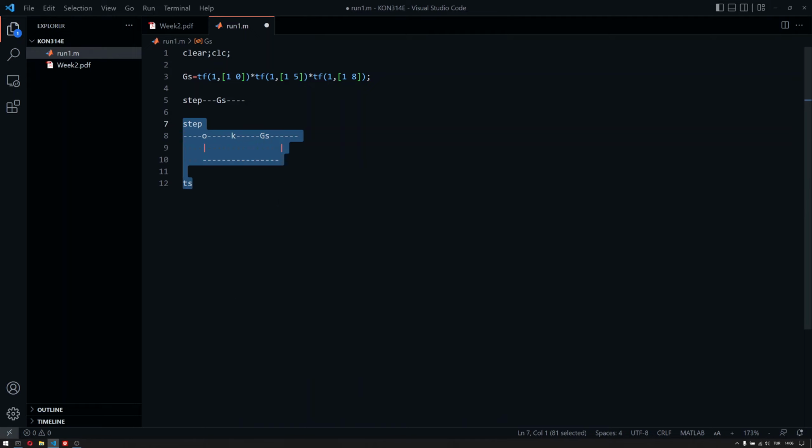So that's our aim. Now, of course, we've talked about the unit feedback loop here, which was considering the poles of the closed loop. So we have a tool called the root locus plot in order to vary this coefficient k and see what the poles are doing. But these poles don't transition into transient measurements like settling time, overshoot, rise time, peak time, etc. So it has no direct connection to applying a step input and observing the output. Therefore, we need to make that connection.